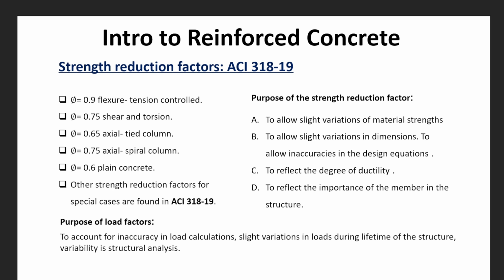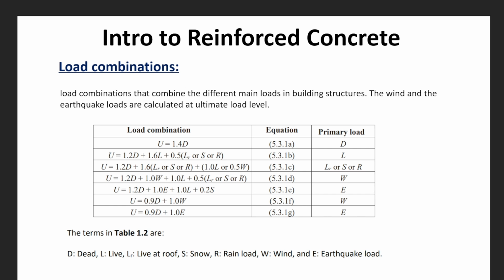The purpose of the load factors is to account for inaccuracy in load calculations, slight variations in loads during the lifetime of the structure, and variability in structural analysis. Lastly, the load combinations: these combine the different main loads in building structures. The wind and earthquake loads are calculated at ultimate load level.